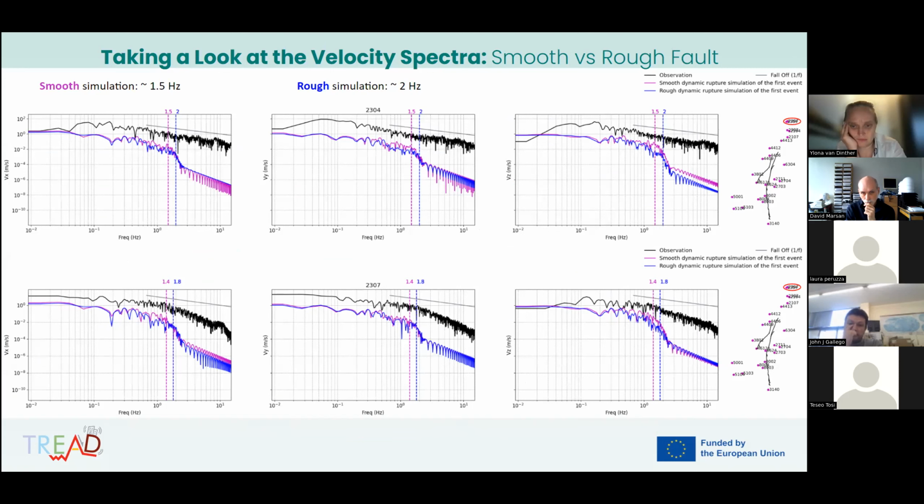At this point, I interpret the fact that we resolve higher frequencies closer to the fault because the mesh is at a much higher resolution as you approach the fault. So in the two cases, the mesh size is also variable. Okay, yes, that will then probably be the explanation for the distance. Okay, thank you. Thanks, Ilona.